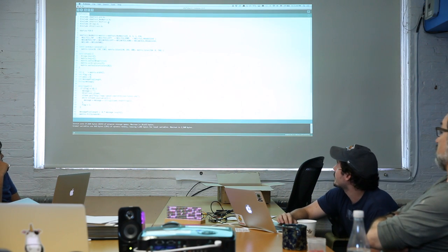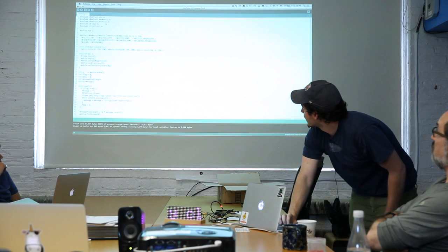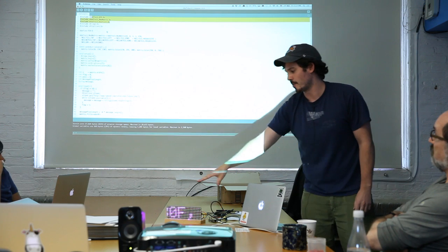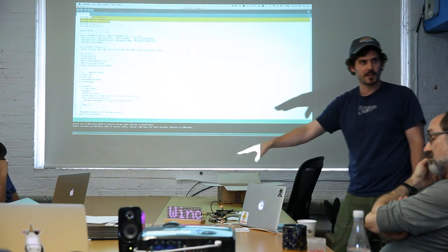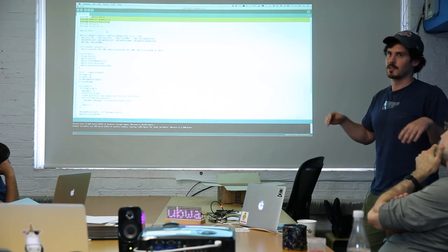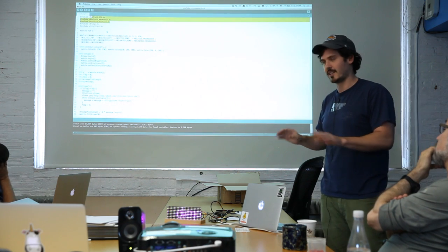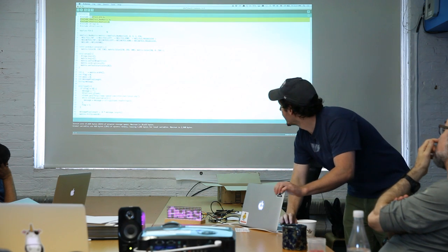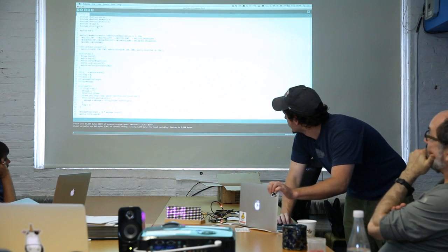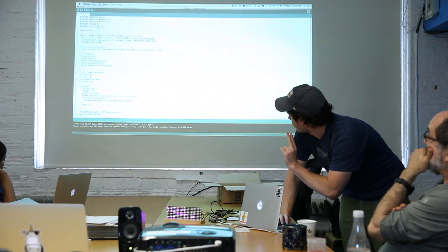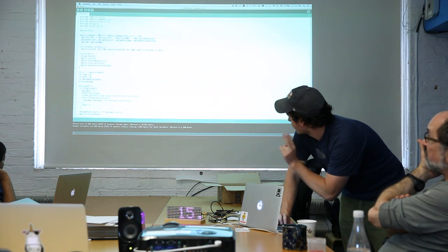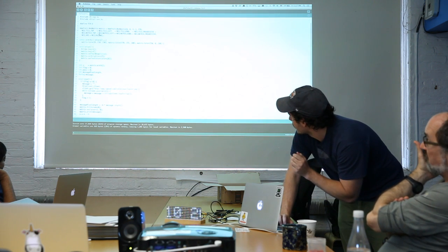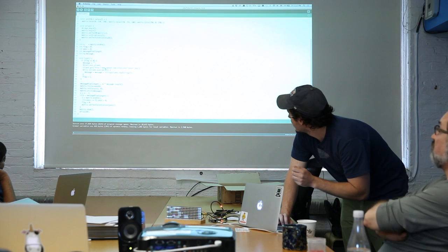So from the top down, these first two are libraries for communicating specifically with these LED boards. There's a certain protocol, and there's already a library built. You include them, and it does all the thinking for you. There's no math involved in figuring out how to make this message go across. Bridge is what I was talking about before, to allow the two sides of the Arduino to talk. An HTTP client is going to use Bridge to make HTTP requests.